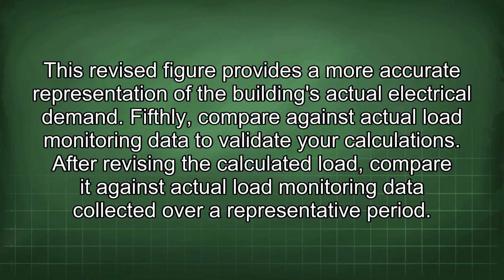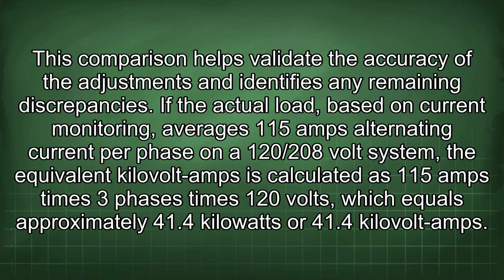Fifthly, compare against actual load monitoring data to validate your calculations. After revising the calculated load, compare it against actual load monitoring data collected over a representative period. This comparison helps validate the accuracy of the adjustments and identifies any remaining discrepancies.